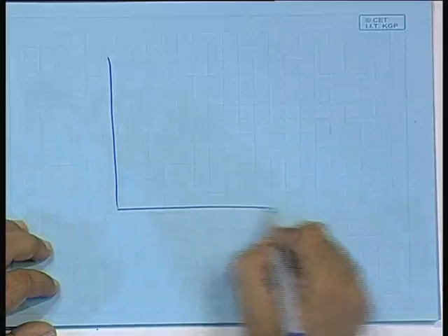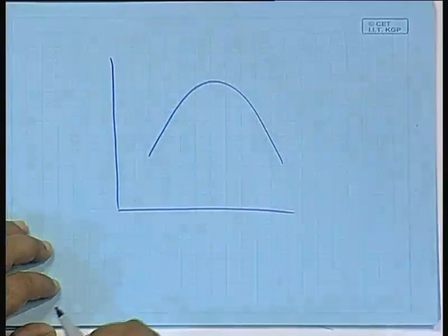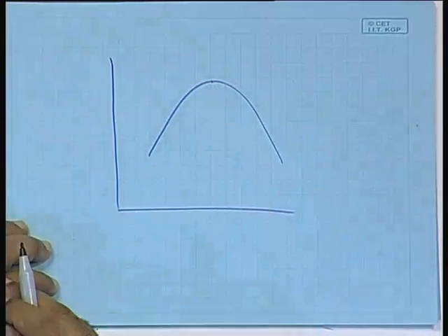For any maximum tracking problem, the other approach is that if you multiply the voltage and the current, that should be maximum. Now, suppose there was some duty cycle, you change it a bit, and see, the character of the power curve is something like this, and you are trying to operate here.